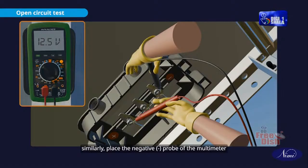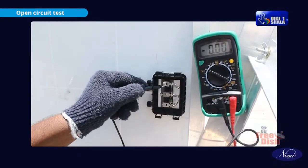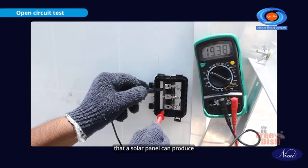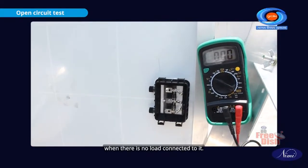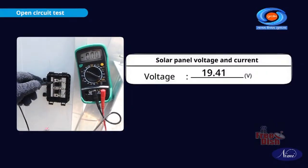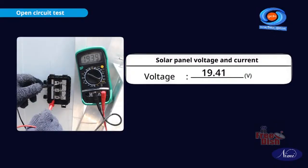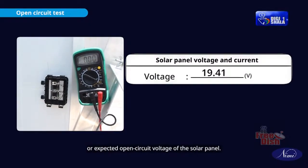Similarly, place the negative probe of the multimeter on the negative terminal of the solar panel. Measure the open circuit voltage of the solar panel. The open circuit voltage is the maximum voltage that a solar panel can produce when there is no load connected to it. Take a note of the voltage reading displayed on the multimeter. This is the open circuit voltage of the solar panel. Compare the measured voltage with the rated or expected open circuit voltage of the solar panel.